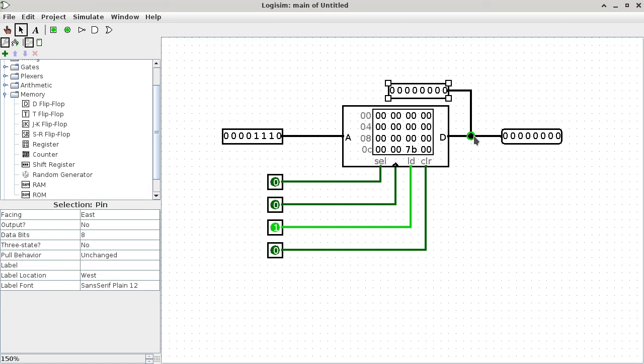That should not be a problem. And it's also okay for this to connect to the RAM component for now, because the RAM component has a chip select of 0, which means the RAM component is saying, just pretend I'm not here. I'm not going to try to change anything. So there's no problem at this point.